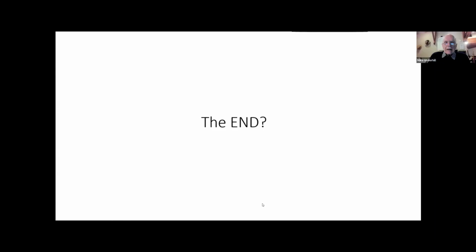Steve Barlow then asks, do SAR mitigation sensors have to be treated as safety critical? Absolutely. So we have backup. If the SAR sensor fails, there is software in there that backs off the power 100% all the time. Let's say my SAR sensor didn't work for whatever reason. There's a backup that says, your sensor doesn't work, so I'm going to back off 100% of the time and effectively cripple the transmit power to safe levels. The user experience will be dropped heavily because of that.